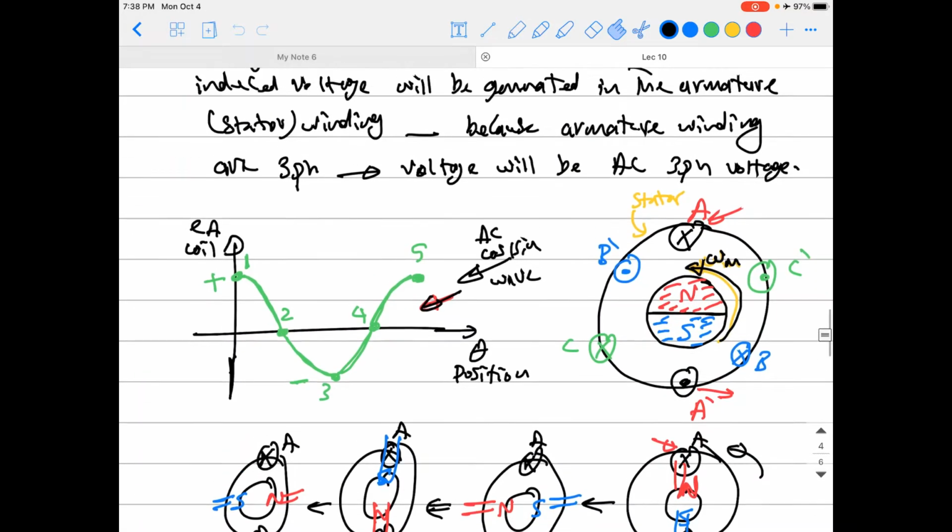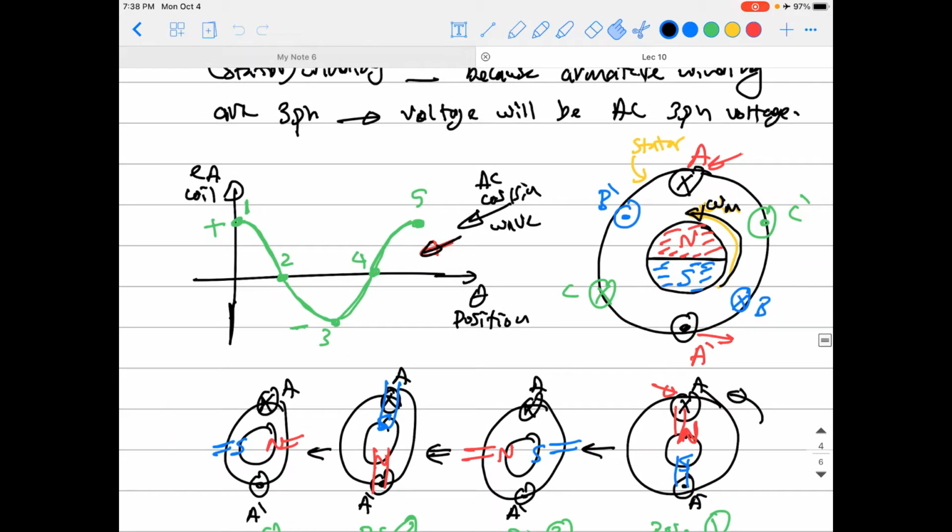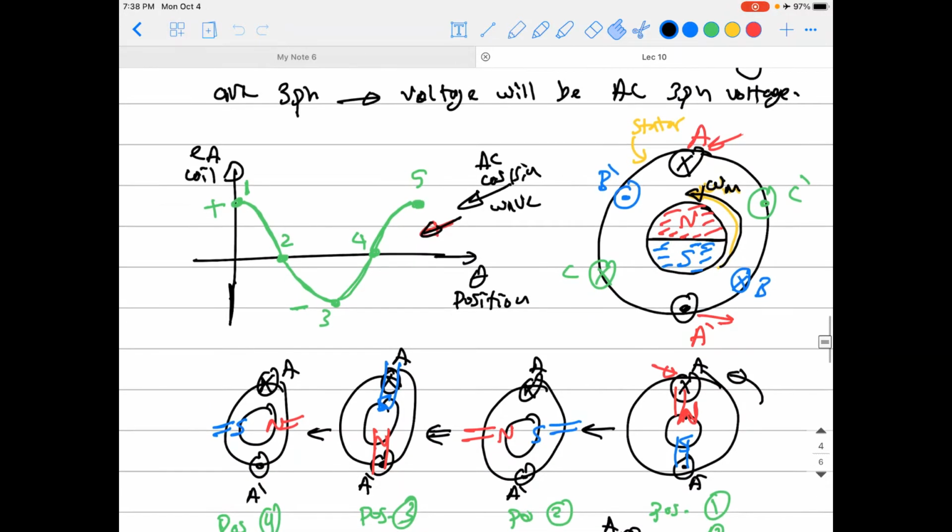So we just had time to illustrate how the voltage is generated from that kind of machine. So the rotor holds the magnetic field source, which is basically north and south pole. For this very simple illustration, we just use a two-pole machine, just one north pole and one south pole, and figured out that if we apply an external source to rotate this rotor forcefully inside the stator, the magnetic field coming from it will cut the winding in the stator, and this will produce induced voltage in it.